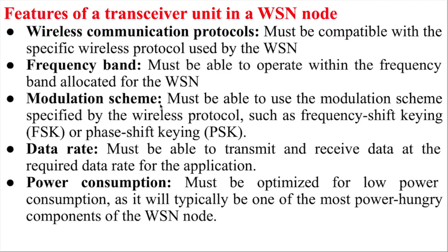Another is the modulation technique. Since there are a large number of nodes, if you are not using a modulation technique, you are not able to transmit multiple data simultaneously. So modulation changes the format so that you can transmit the data simultaneously, and nodes can receive, demodulate, and extract that information. Such as frequency shift keying, FSK, or the PSK modulation technique, and change the data.